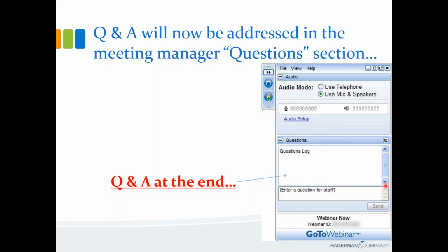Can the part names be changed to follow a part numbering scheme set up with Vault Workgroup instead of the default part numbering? The part number is pulled from the Content Center, so whatever you have listed there, it's going to follow that sequential setup. Once you get this into Vault, you can renumber parts from there. As we place it, there's no way. They don't have it in the software to pull a queue or reference into a Vault table to say, get your part number from here. It has to be mapped into the Content Center in the fashion you need it.